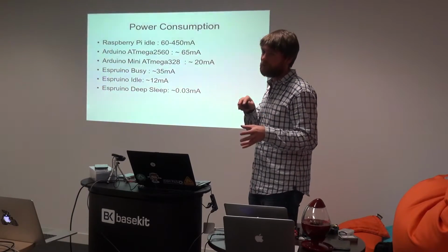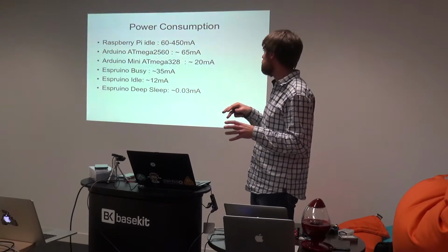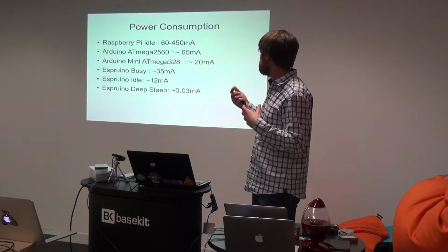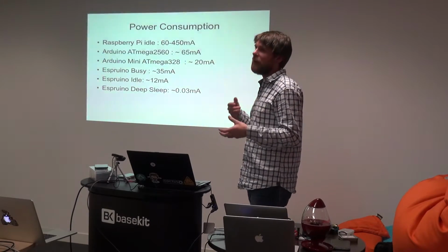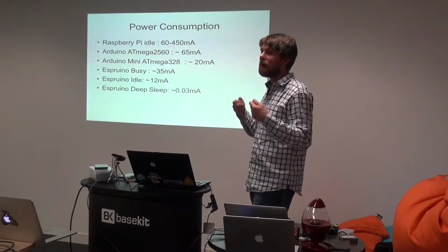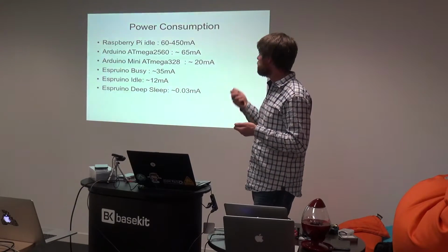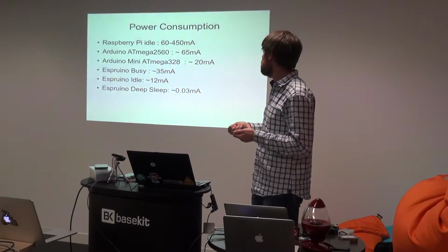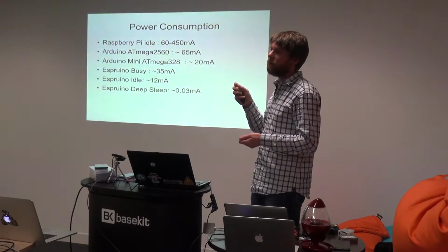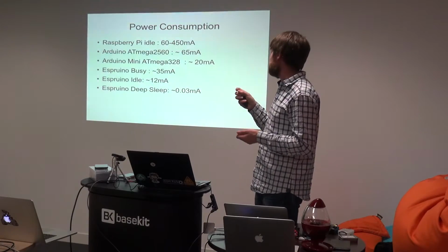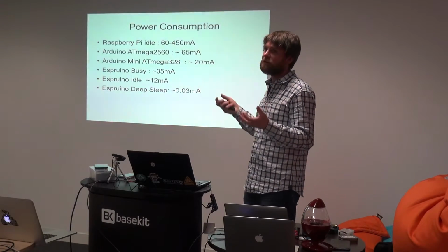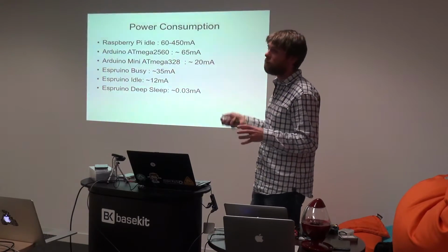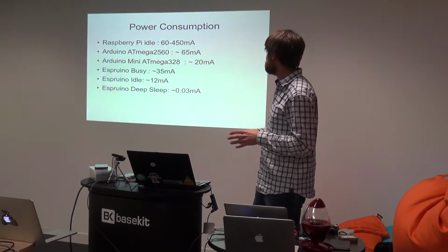One of the reasons is they don't have a real-time clock properly built into them. But generally, trying to set everything up so that it wakes up at the correct time is quite difficult. The Arduino boards are not really designed for low power at all, and they generally use voltage regulators that are designed to power quite beefy devices. But because they're designed to produce a lot of power, when no power is being drawn, they're actually quite inefficient.